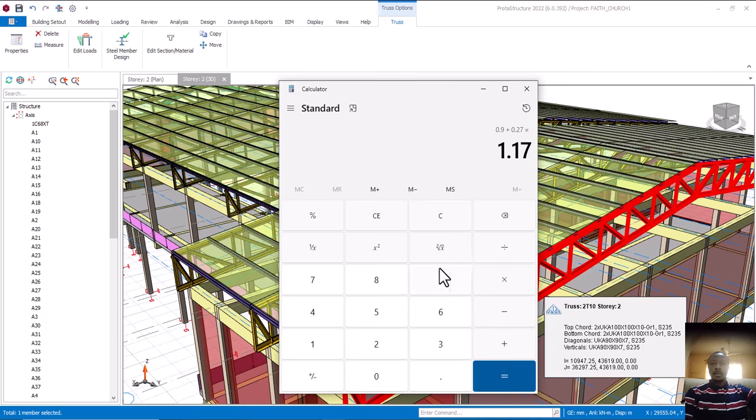Now, if you use 0.75 as dead load, what does that mean? It means that you are not applying the live load factor. We are only going to apply the factored load of dead load. And you know that our dead load factor is 1.35, isn't it? 1.35.